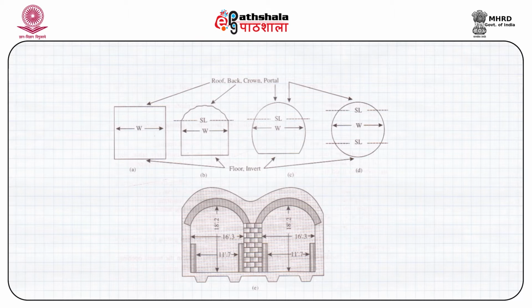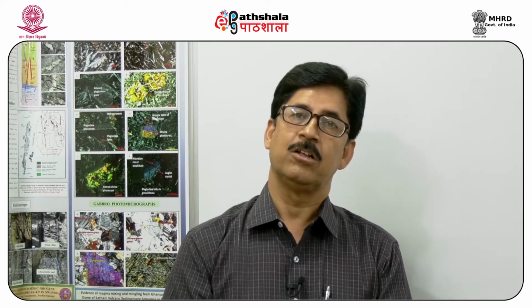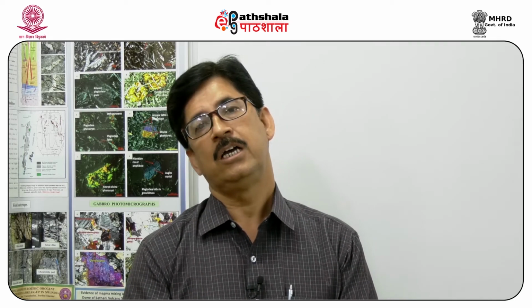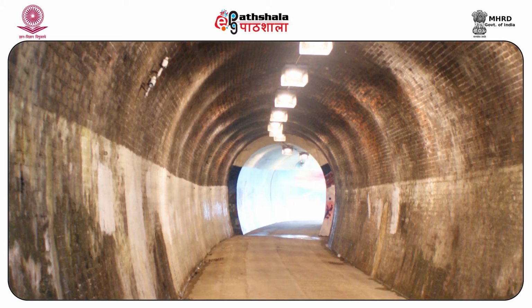Most of the water pressure tunnels which carry water from the reservoir to the turbines for generating hydroelectricity are circular tunnels. Most of the tunnels which are made in soil or earth are usually square section tunnels. But tunnels in the rocks are mostly arch tunnels or horseshoe shaped tunnels. The most important part of the tunnel is the portal or back of the tunnel, that is the ceiling of the tunnel, followed by the walls of the tunnel and then the floor of the tunnel.